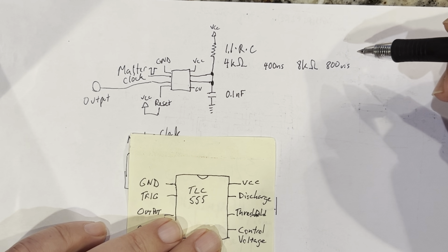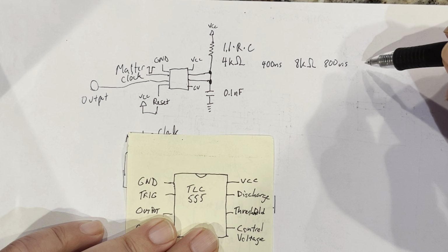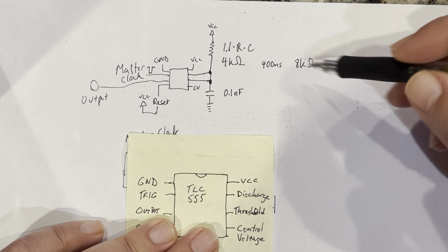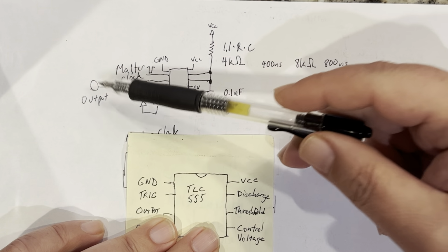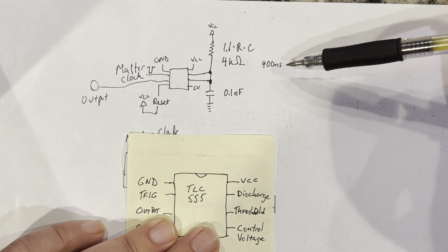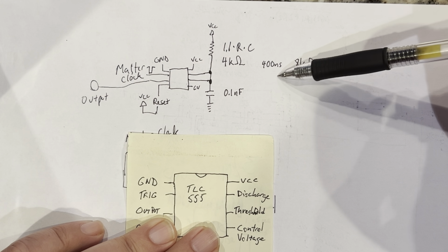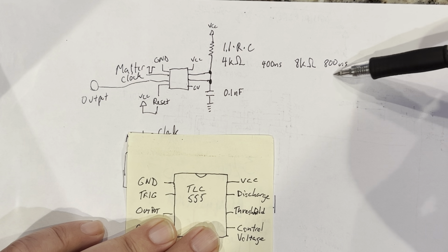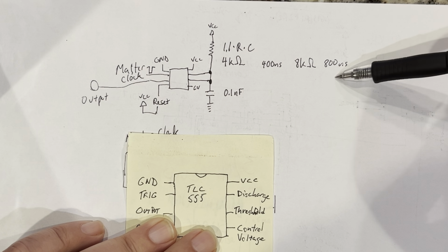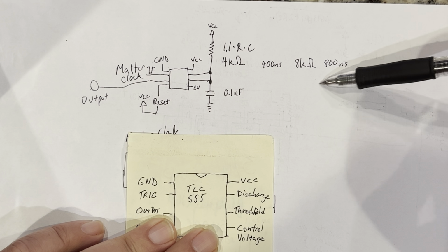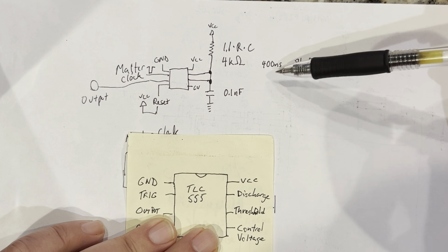And it wasn't until I put an oscilloscope on there that I realized that the actual output coming out of this, I could not get any pulse that was this low. I could get it to maybe 850, 900, which is still okay within the tolerance of the high pulse. So that's why the NeoPixels were turning on. But I could not, for the life of me, do anything to get this pulse low.